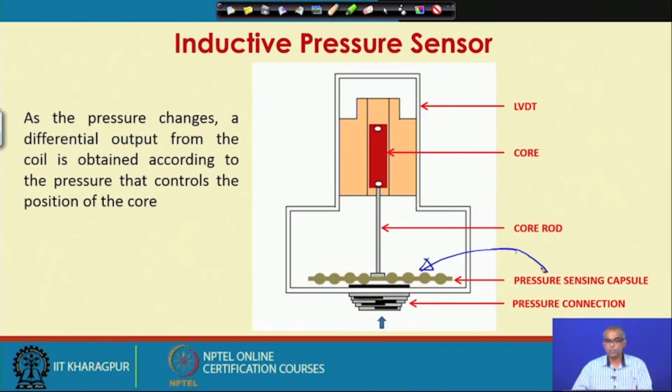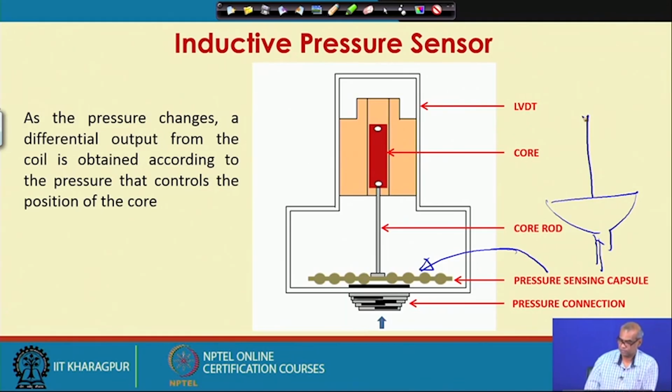To understand the working of this inductive pressure sensor, you can also consider the pressure sensing capsule as a simple diaphragm. To this diaphragm, I have attached the core of LVDT. Now, I apply pressure inside.